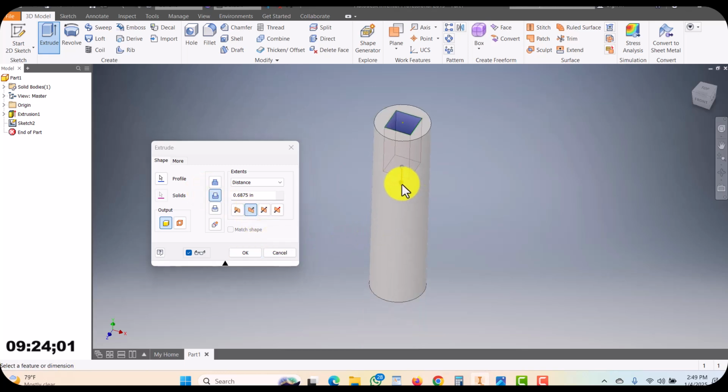So I can also use extrude to cut hole material. So extrude can also do that. It can either add material or remove material. So use the cut option to remove material. And be sure that while you are using the cut option, your direction is cutting through. You have to specify a direction that cuts through the initial material. So that's the difference between join and cut.